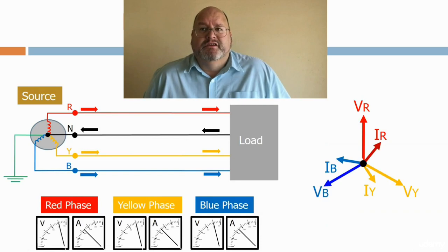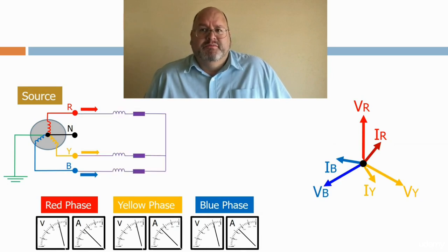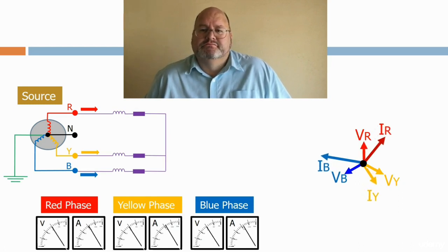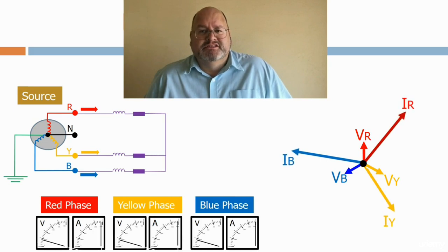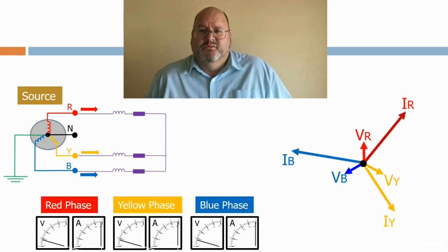Finally, let's now look at a full short circuit across all three phases. The impedance of the faulted circuit now represents a balanced fault, consisting of only the phase conductor impedance on each leg. Let's see what happens to the voltages and currents. As we can see, all three-phase current magnitudes increase significantly and flow equally between the three phases. We now have line currents instead of phase currents.